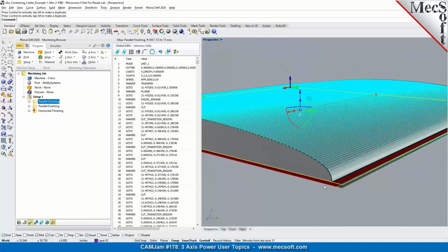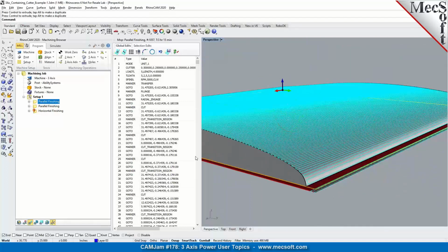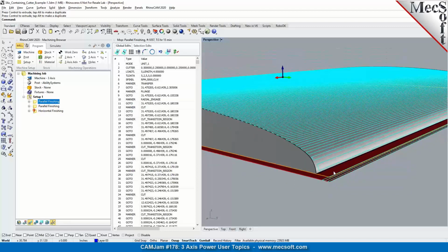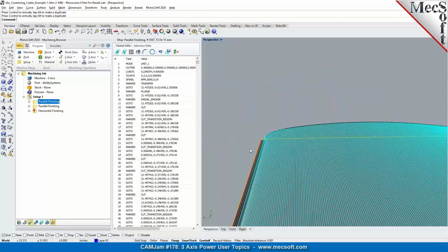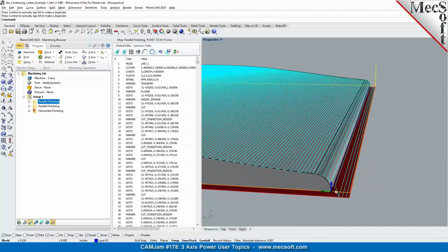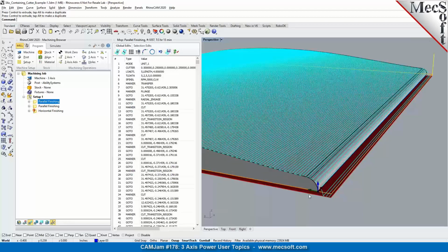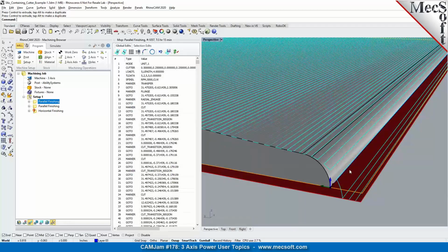The same thing goes whether the angle of cut is 0 or 90 degrees; you'll have the same effect. To be able to cut down fully on the sides, you'd want to make sure that you offset it by the cutter radius. That would be the minimum distance that you want to offset it away from the edge. This would be helpful in parallel finishing operations. It could be for any type of part that you're working with. This is just an example to illustrate that. I'm now going to be going over a few other cutter containment examples.